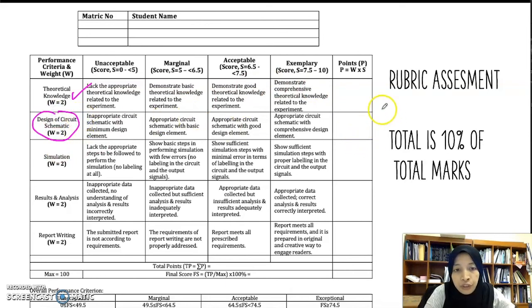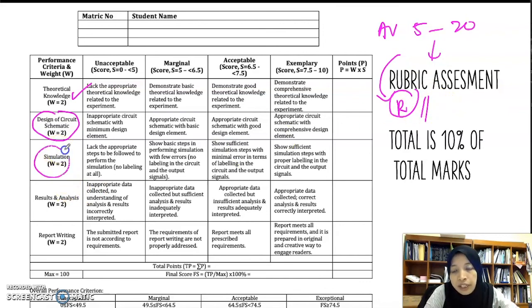From there, you're going to decide your gain in the range of 5 to 20. Choose one number between 5 and 20, and then you derive how you can get the value of the unknown resistor, either in series or in parallel. Then you simulate your op-amp design in both: one is PSpice and the other is Tinkercad.